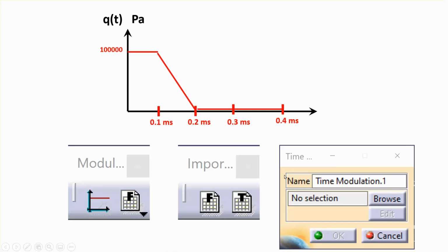You don't have to give it a curve. But if you have a variation like this, then you have to give this information to it, and it's going to be done through an Excel spreadsheet, or you can do it through a text file too. But I'm going to use an Excel spreadsheet. See that this was constant white noise. But if you have variation with time, then you have to input it in the form of a curve.